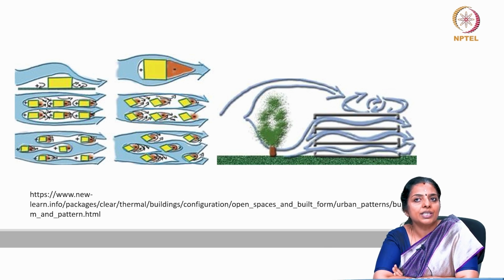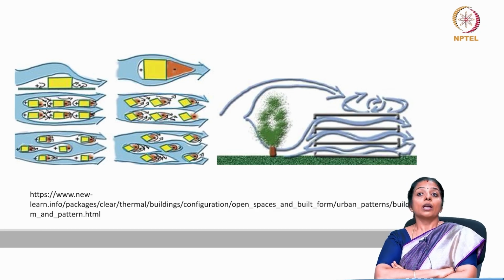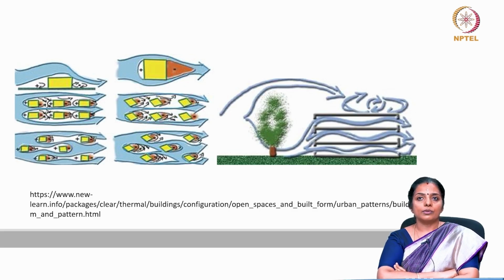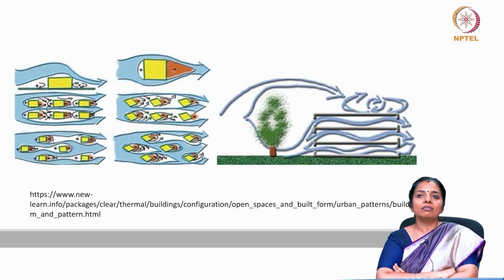Depending on the relationship between the wind direction and that of streets and buildings, there may be variations in wind speed. When large built volumes, or say a long row of buildings, are placed perpendicular to the wind direction, then shielded zones are established between the buildings, where wind speed might be just a small fraction of the speed above the building's roof, or in streets parallel to the wind direction.